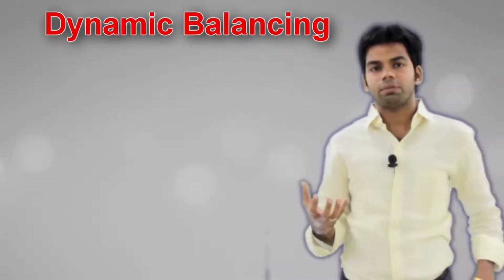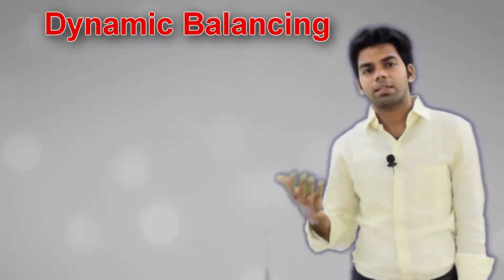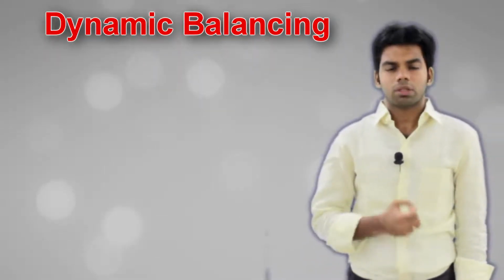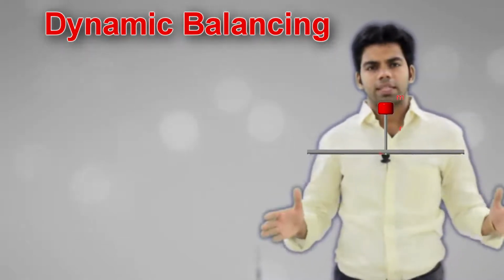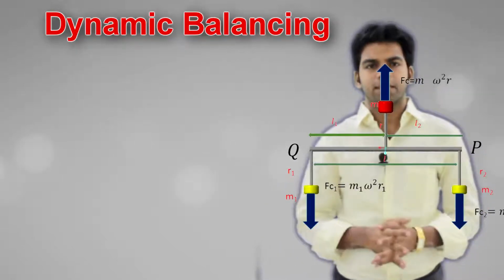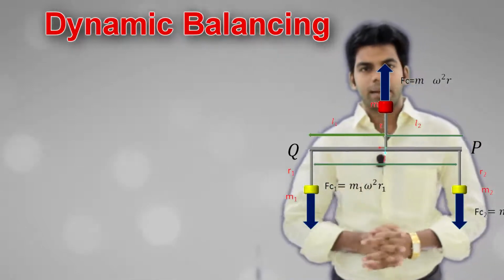In static balancing we were balancing only unbalanced inertia forces. In dynamic balancing we have to balance unbalanced inertia forces as well as the unbalanced moment. So suppose we are considering the same case, where we have one unbalanced mass m. Now we are putting masses m1 and m2 at two different planes q and p respectively, and the distances are l1 and l2 respectively from the main mass, the unbalanced mass m.